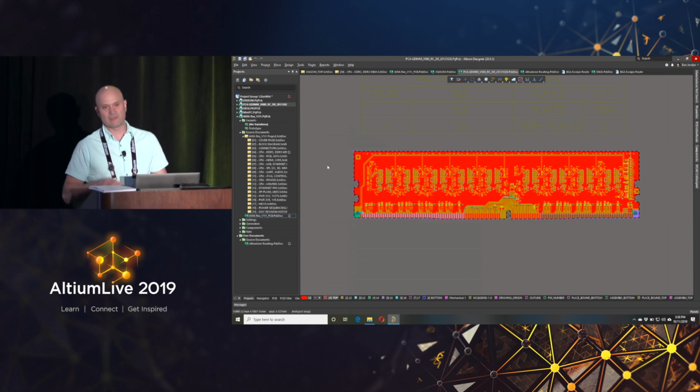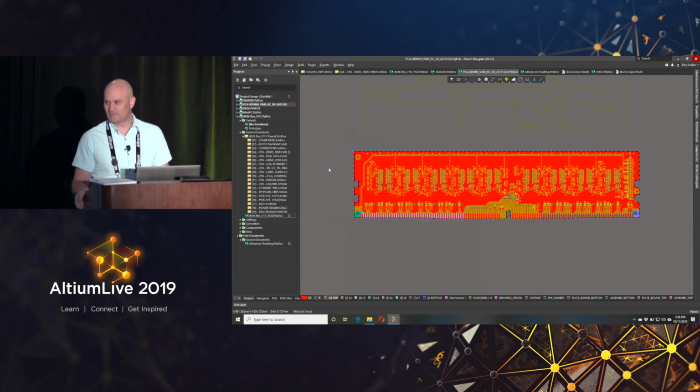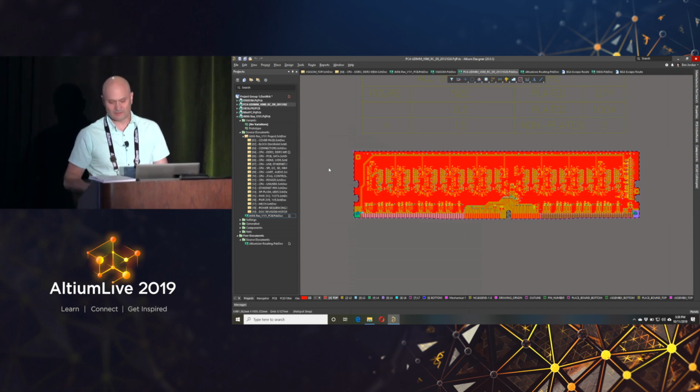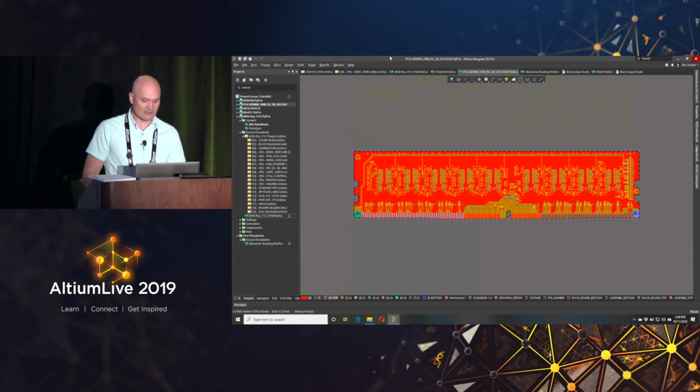It's about having good return path and power planning. And Susie, you mentioned sometimes signals will couple to power nets just as well. Well, they'll do that well if you have good capacitors on your board, right? And good high capacitance. So thin layers. So Layer Stack Manager is really probably the first place where you need to put in a bit of effort.